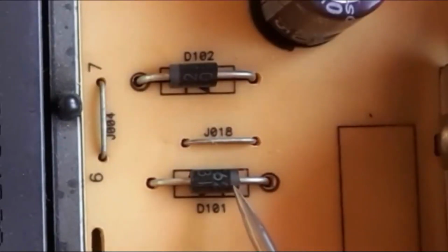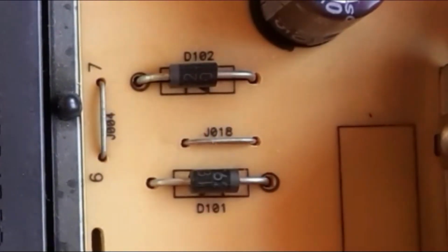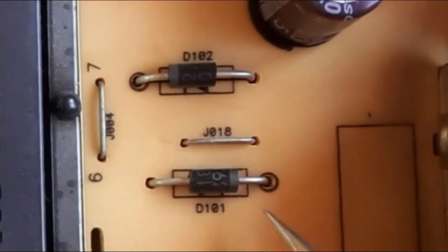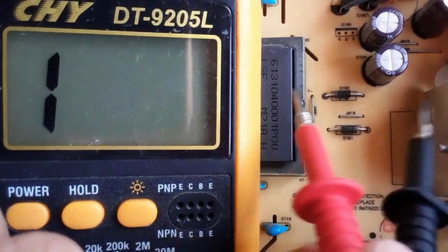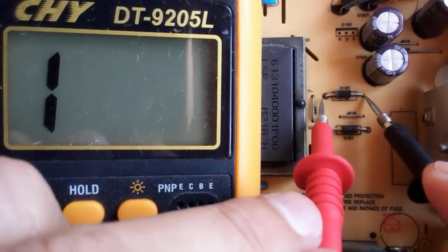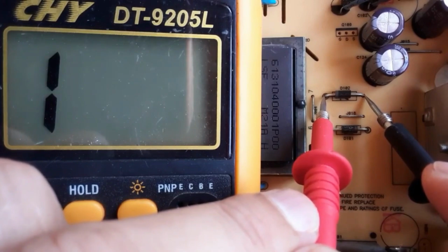Normal diodes are distinguished by their anode and cathode. It is vital to ensure proper probe placement for accurate multimeter readings during testing. To check a diode's functionality, the measurement of voltage drop is crucial, along with ensuring that no reading occurs when the probes are reversed. This result confirms a healthy diode.